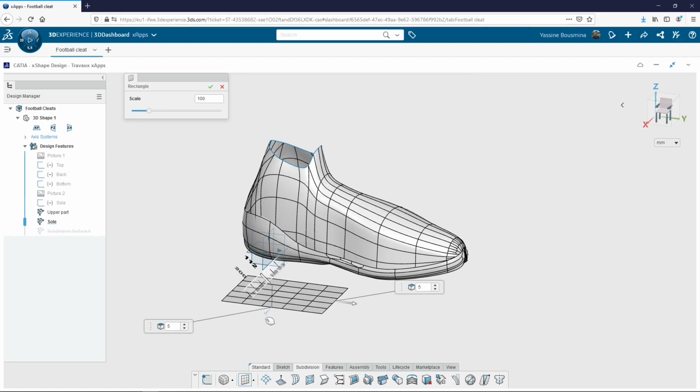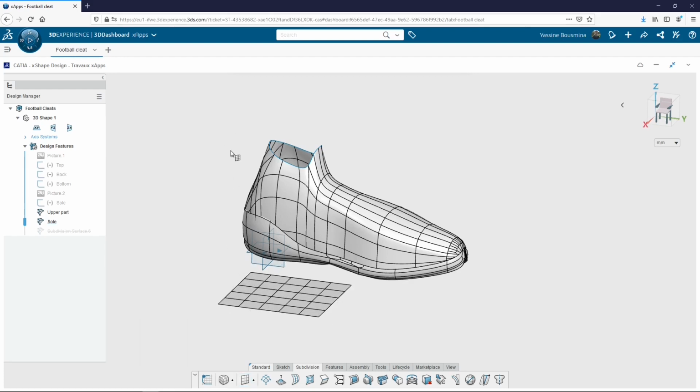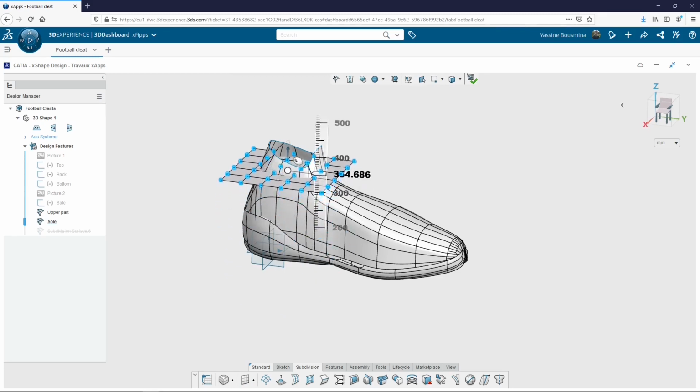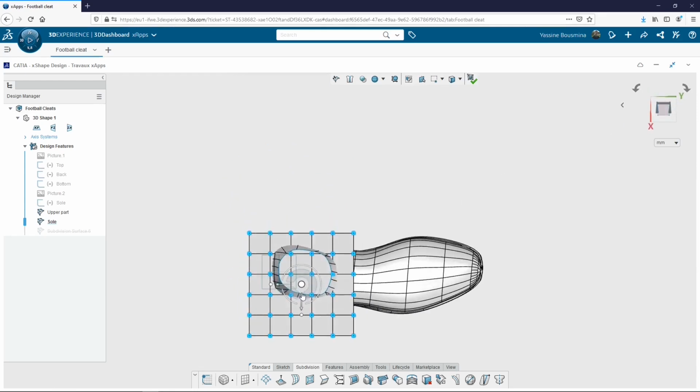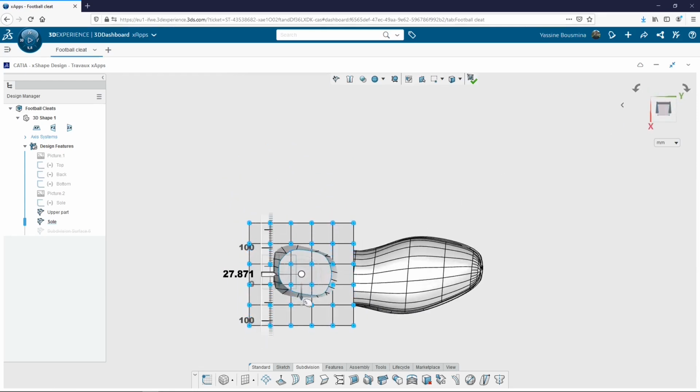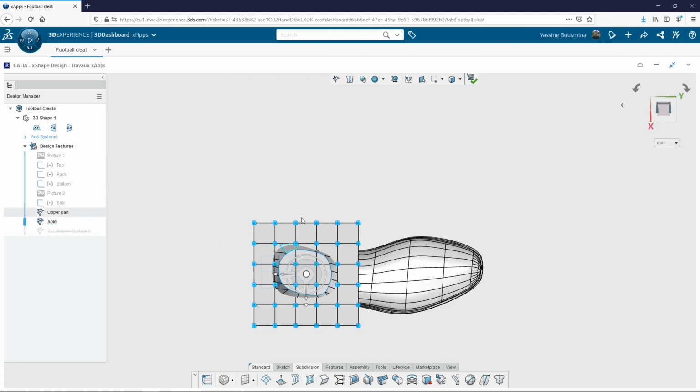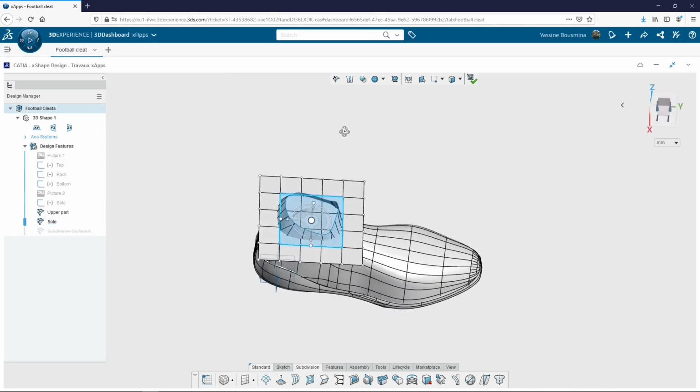I will use these crossing surfaces in the XGenerative design app to cut the upper part into several surfaces and give them different colors and features. For the first surface, I want to delimit a part at the level of the ankle, thus I place it near the shoe's opening. I make sure that this surface completely crosses the upper part and I curve it the way I want.